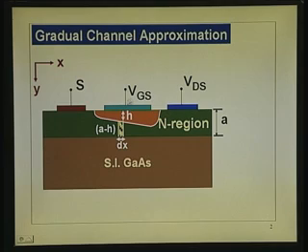So, we have used terminologies VGS, gate to source potential, and VGS has a positive value if it is forward biased, VGS has a negative value if it is reverse biased. And we also saw in the previous discussion that when VDS, drain source voltage, is small, the drop along the channel length is small. This region is called the channel. So, drop in the channel region is small, and the voltage across the depletion layer is constant from the source to the drain end.